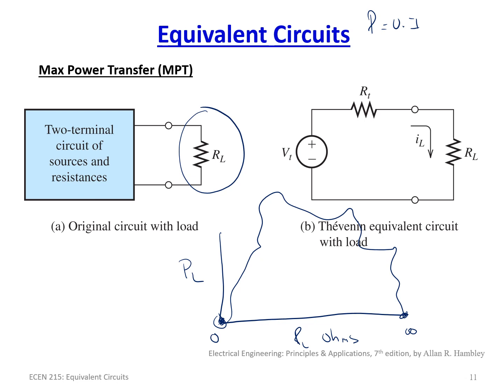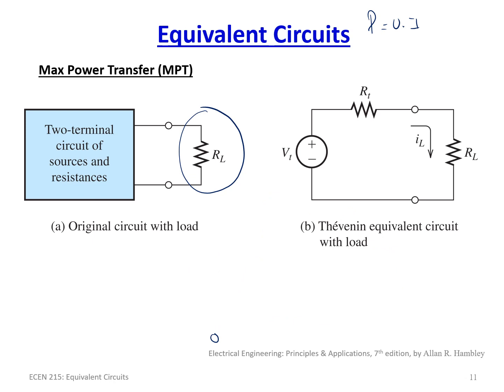But there's going to be some sort of relationship that's obviously going to start out at 0, increase and go positive for power, because this is going to be an absorbing device. So it doesn't have negative power. It's a resistor. So it's going to increase in power, and then at some point, it's going to start decreasing. So we're going to take a look at what this formula is. You can do the circuit analysis and easily figure this out, but I'm just going to show you real quick what you really need to know. When it comes to the test and the homework, the only thing you really need to know here is where is the point where it's maximum.